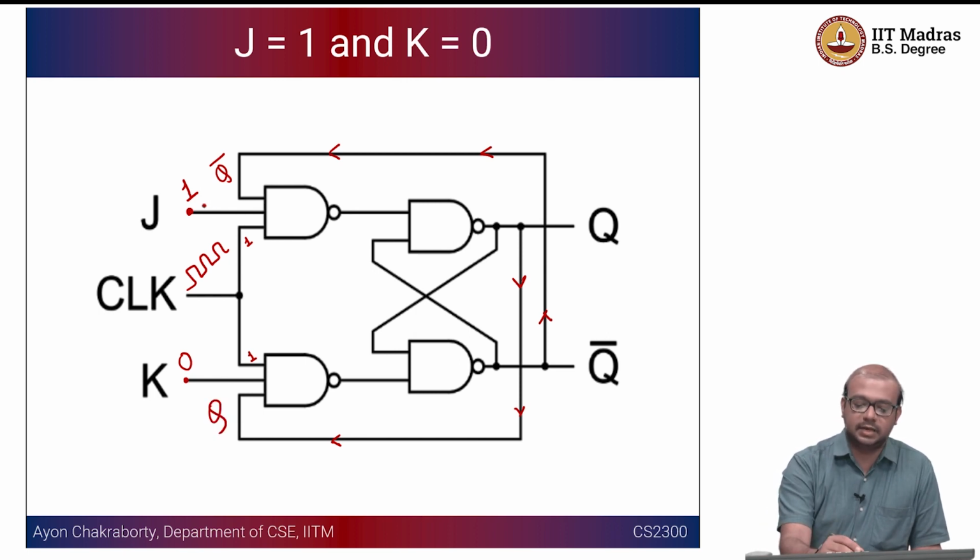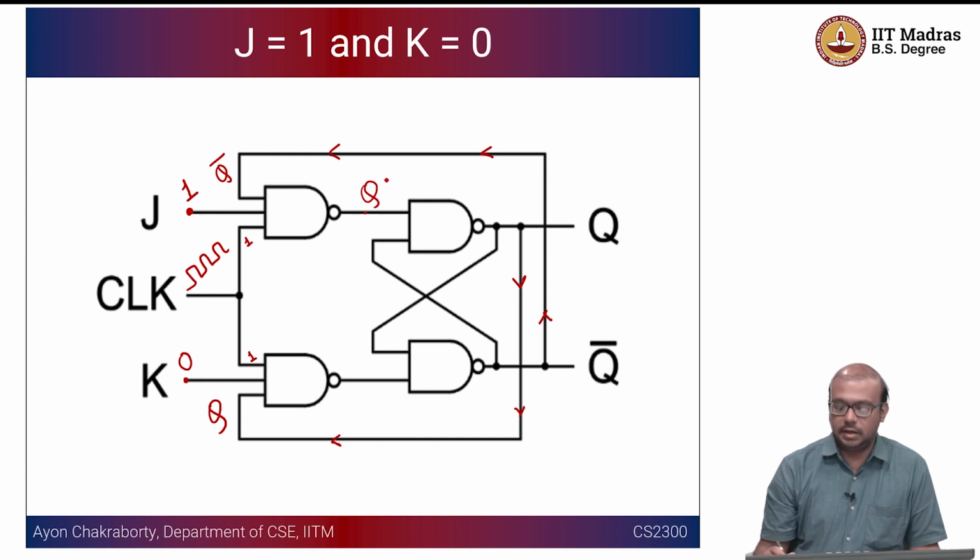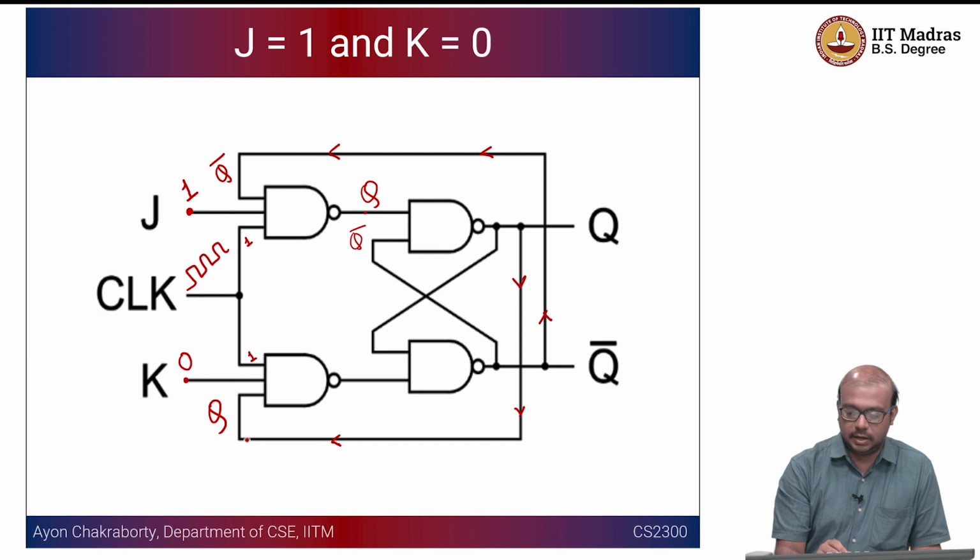So similarly in this case also, you can see 1.1 q bar is going to be q bar only, and you are taking a complement of that, so this becomes q, correct? And here we have to see that this is actually q bar, right? And we can kind of q dot q bar here. So this is an input which is ANDed, rather NANDed. So q and q bar is going to be 0 and the NANDed value is going to be 1, right?